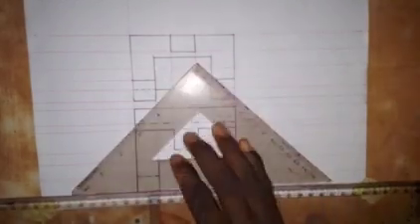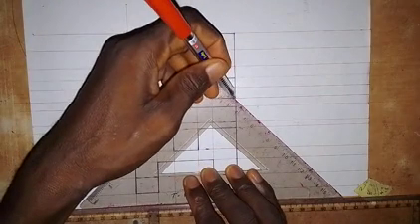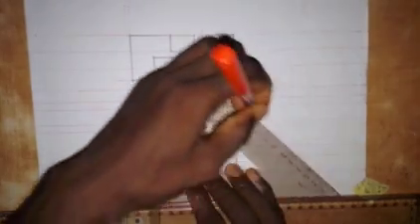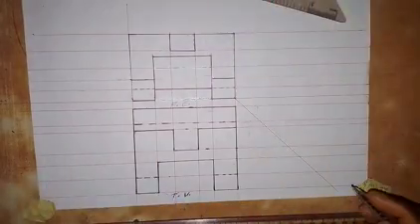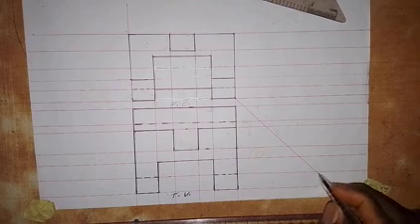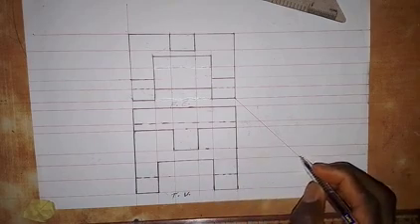Now let's go for the end elevation, and we are only drawing the left end elevation, which will be placed on the right side, because these views are being drawn in first angle orthographic projection. With the 45-degree set square, set at this point on the front elevation, we are to draw a line in this direction. So we have this line. From each point where this inclined line intersects the horizontal lines that we drew out of the front of the plan, we are going to draw a vertical line.